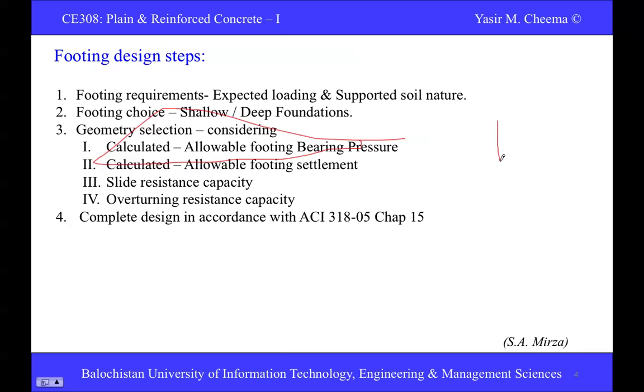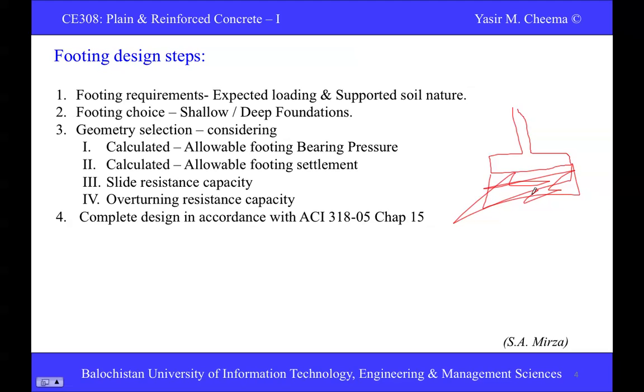Let's say this is your foundation, and this one is soil below here. So how much this soil can support the pressure, how much this soil can bear the pressure, this is the allowable bearing pressure of the footing, how much soil can support. Secondly, the calculated means how much pressure is being applied on this footing.